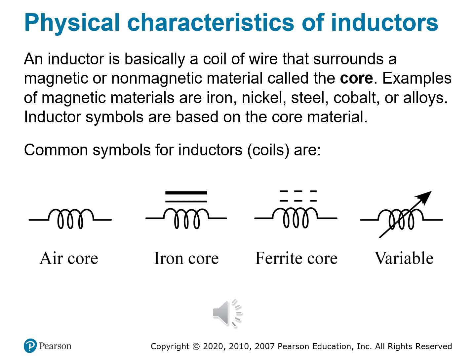Then we have the iron core next to it, iron or steel, and this increases inductance significantly. These are common in power inductors and low frequency filters. Next to that, we have the ferrite core, and that's made from ceramic plus some iron compound. These are efficient at higher frequencies. They're ideal for transformers in switch mode power supplies, and they minimize what are called eddy currents. And we'll discuss eddy currents later in this course, or in this podcast, excuse me.